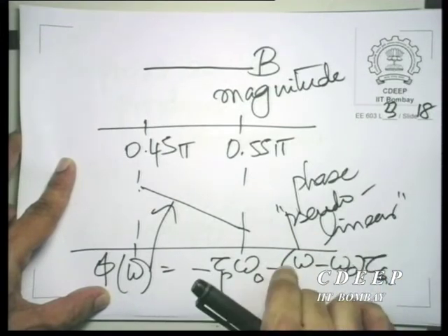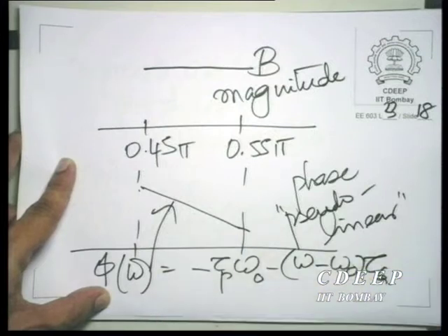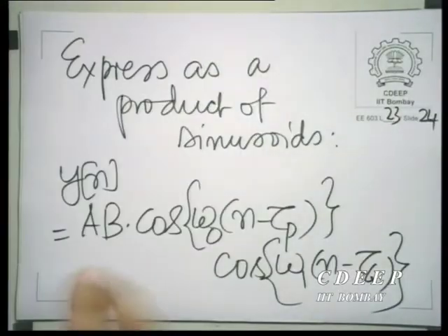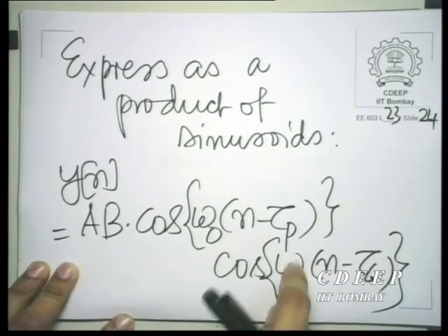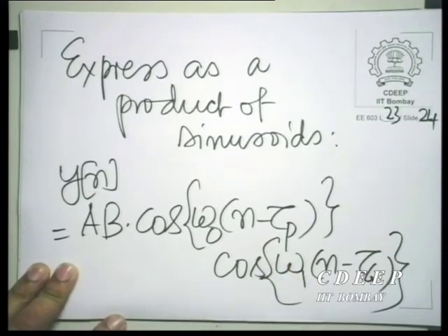And the significance of the group delay is that it acts on the message, and the significance of the phase delay is that it acts on the carrier. That is what we have been able to demonstrate by this question. Here, we demonstrated it exactly when you took a message which was exactly a sinusoid, a very narrow band message. But you could of course extend this idea if the message had a combination of sinusoids but narrow band.